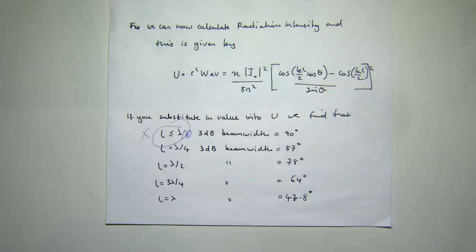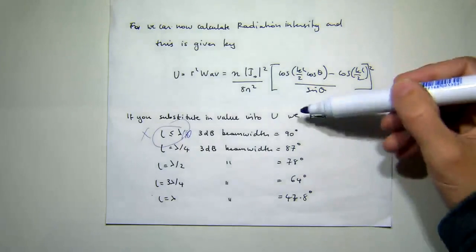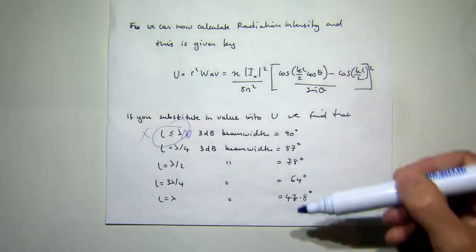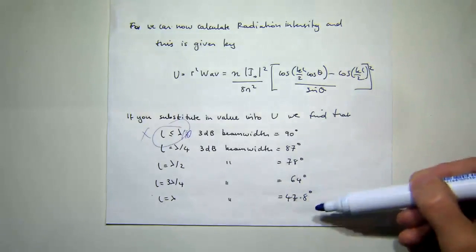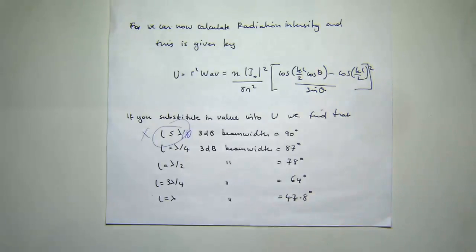So the only thing that varies is the donut, or how wide that donut is in the E-plane. So as we make our antenna larger, or a significant portion of the wavelength, the directivity of this dipole actually goes up, because we've got a 1 on theta type relationship.